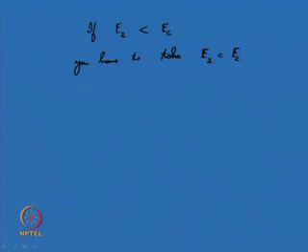So, if your computed E2 comes less than E c, you have to take E2 equal to the critical energy, the specific energy at the critical flow, then compute specific energy at upstream.